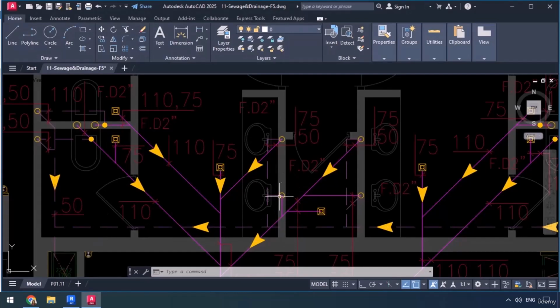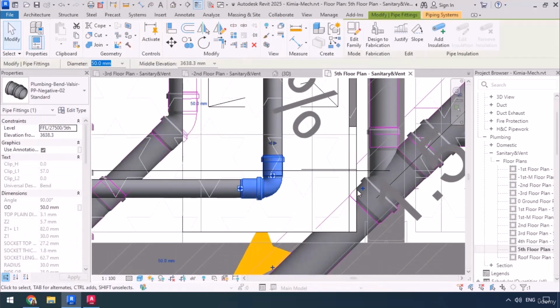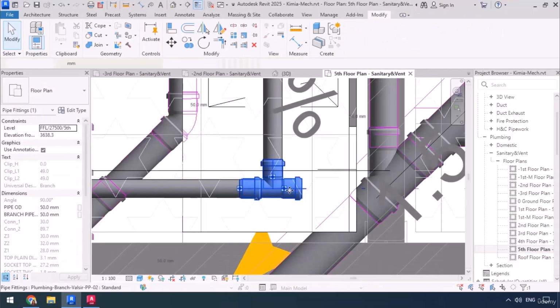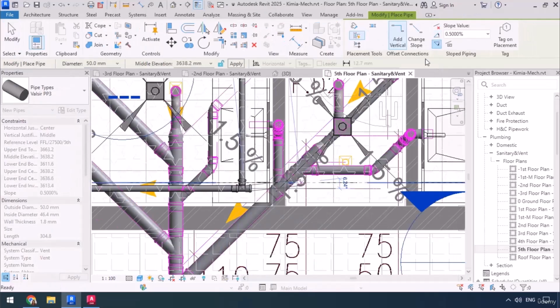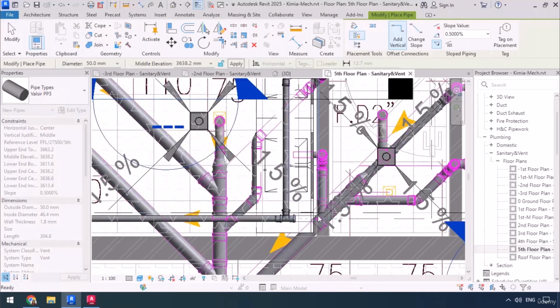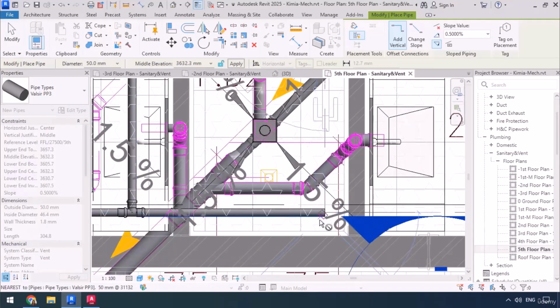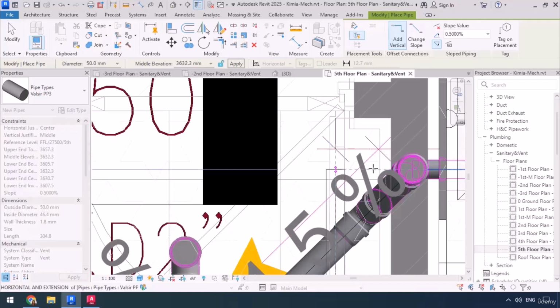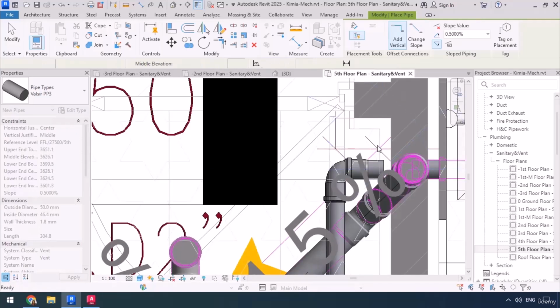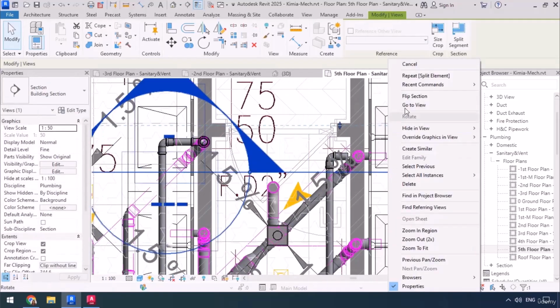Now we're going to have to also draw and connect this next pipe, as well as these others over here. So all these 4 lavatories need to be connected to this pipe. Now I'm going to go over here, select this elbow, click on the plus sign to convert it to a T, right click and draw pipe. And this time we're going to need slope down because we're getting closer to the fixtures. And that means that we're going to have to draw up to here to connect to those lavatories. So click, and then I'm going to go upwards here. Make another click, then draw a little bit of pipe to the right, then click. Now we're going to be drawing the pipes to connect to this lavatory. So we're going to move this section, right click and go to view.